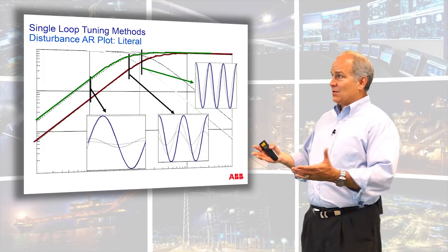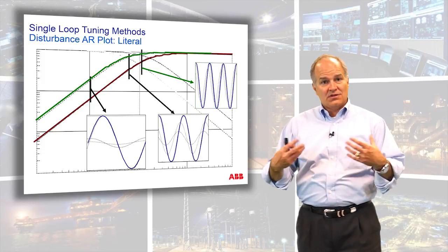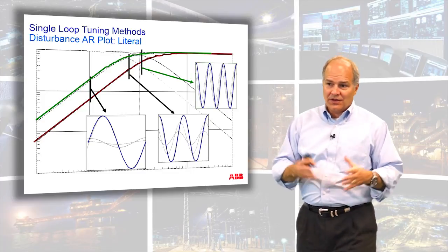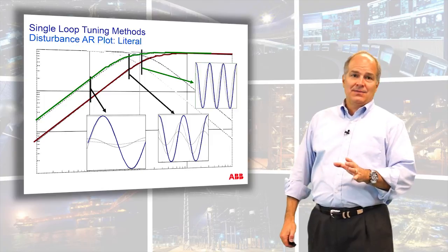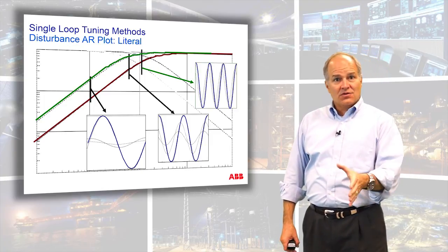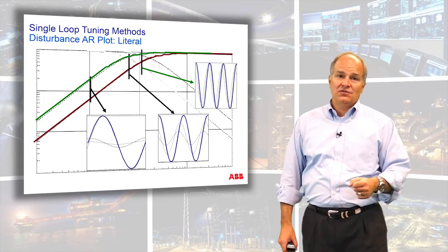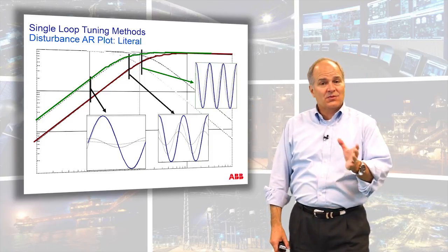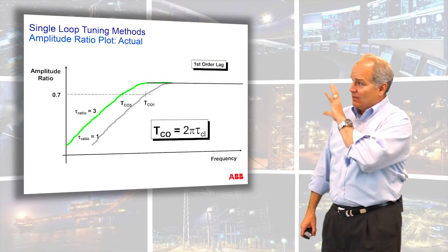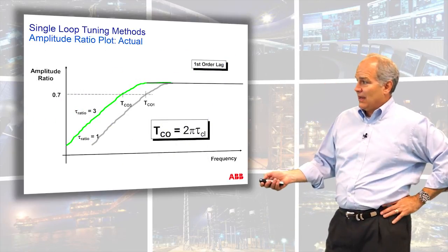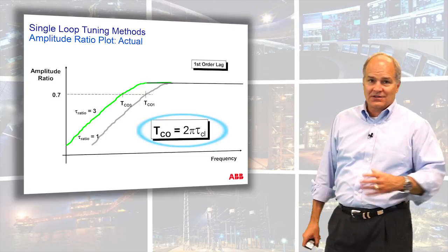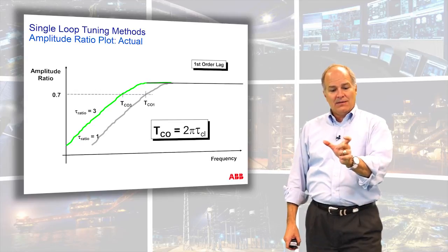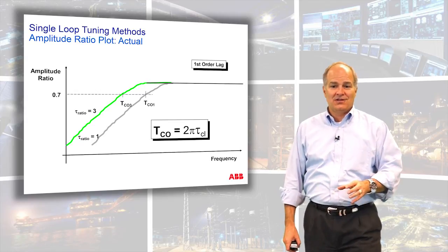So what do you do? That's where you sit down and you look at your P&ID drawings, you talk with your customer and try to figure out where this disturbance is coming from. And then there's a whole other set of analysis. But the ability to say, hey, this is not a control problem, this is a process problem, is huge. And if you flip the control off, you'll see the amplitude get bigger. So by understanding this general picture, by knowing that you can calculate this cutoff period, you don't actually do this test, you don't send in oscillations, but knowing the frequency band because you applied the direct synthesis tuning technique is huge.